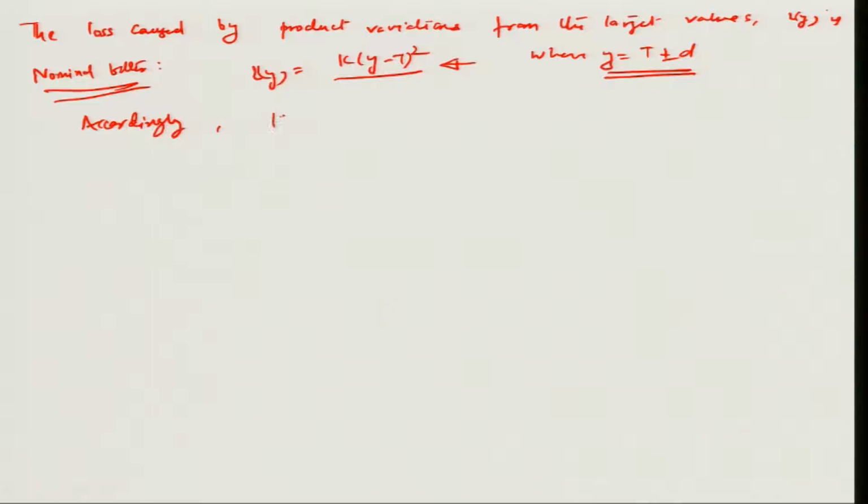Accordingly, the AQL can be calculated, and you can assume the unit cost lost because of the target going away by more than the D value, so that it crosses the USL and LSL, in this case is about $200, because obviously this much cost has to be invested once it goes beyond the 35 RPM range which it is intended to.